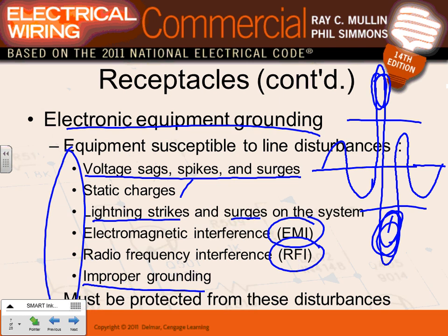There is a standard in a data center that they ground completely different, guys. They even use equipment ground conductor number 4 tied to the frames of the servers in a data center, and this is not enforced by the code. It's enforced by the manufacturers of these sensitive electronic equipment.